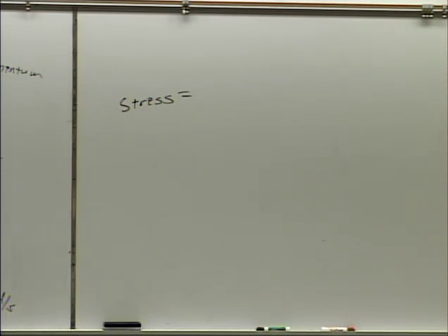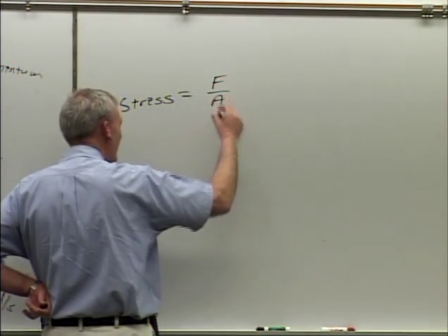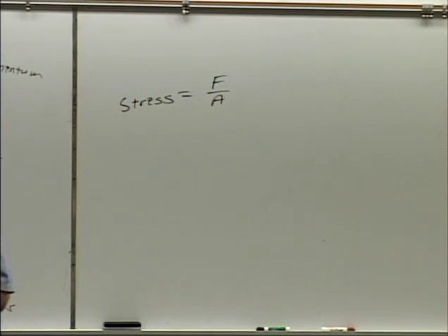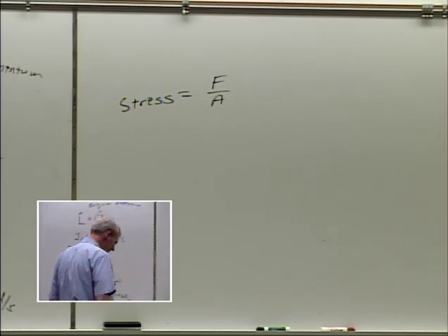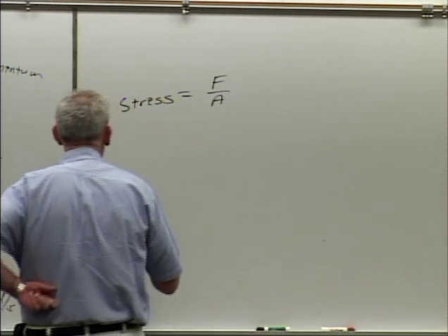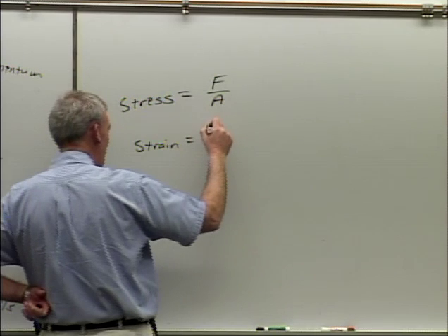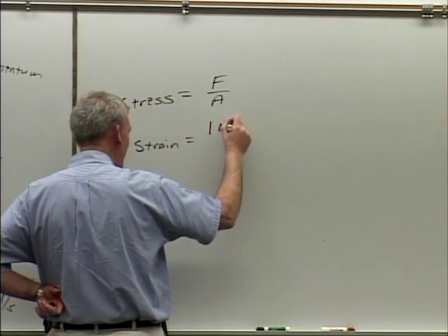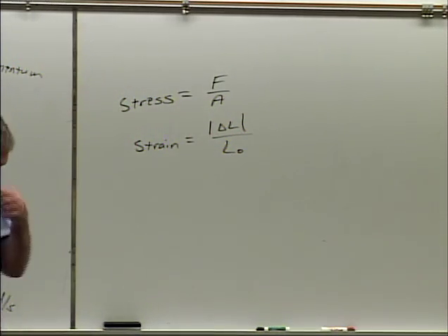Yeah, okay. Stress is equal to F over A, which is the force over the area that I apply the force. That's called the stress on something. So we're going to talk about stress and strain. The strain of something is equal to the magnitude of its change in length divided by its original length.